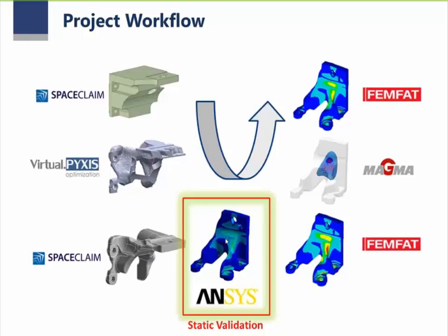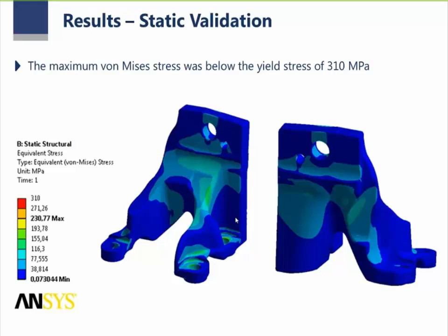After we have this new design, we go back and we apply again those up and down forces, trying to see if, for example, here there is some problem with the component. In this case, for the static validation, the limit is the yield stress, which in this case is 310 megapascal. So it's obligatory that every part of the component is below this, more or less 300. Here you see that everything is below this value, which is approved from static validation.